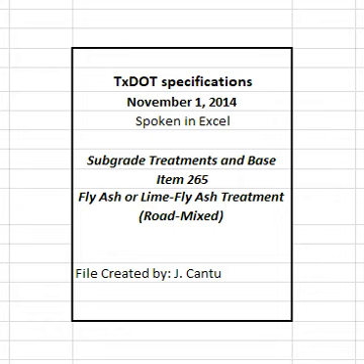5.1.3 Quick lime. 5.1.3.1 Dry. Lime will be measured by the ton, dry weight. 5.1.3.2 Slurry. Lime slurry will be measured by the ton, dry weight, of the quick lime used to prepare the slurry, multiplied by a conversion factor of 1.28 to give the quantity of equivalent hydrated lime, which will be the basis of payment. 5.2 Fly ash. FA will be measured by the ton, dry weight.